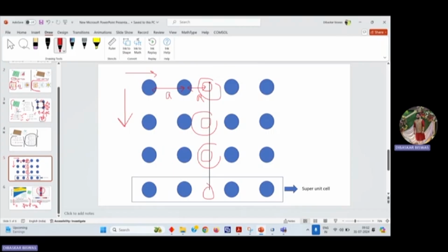If you had removed only one lattice point here, say suppose this is present, then this is present, then also this is present, and suppose we have removed this lattice point, that would have been a point defect. Point defects are generally used for confining the electromagnetic mode in this region only. So these are basically used as resonator type devices, maybe in Q filters and other filters. But if you create a line defect, you are creating a waveguide kind of path. So you are giving a path.